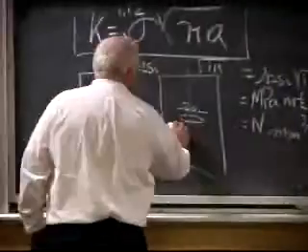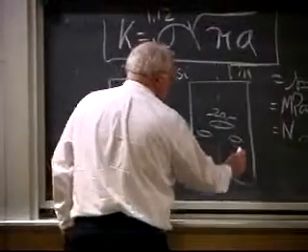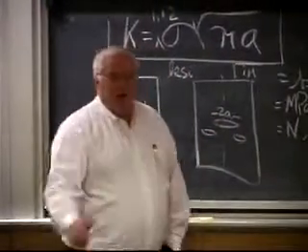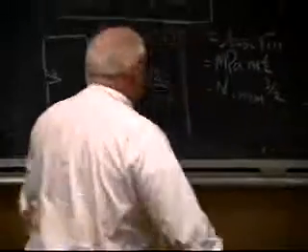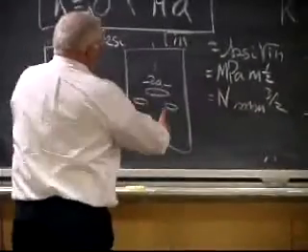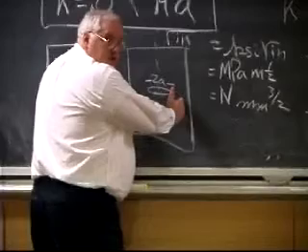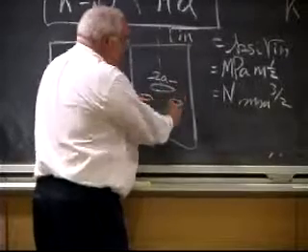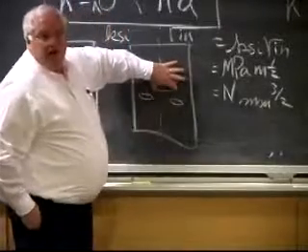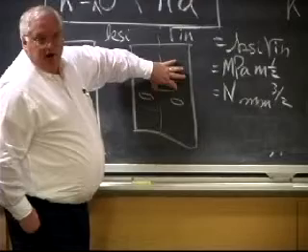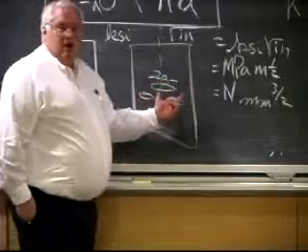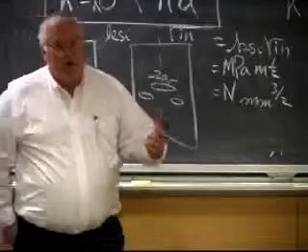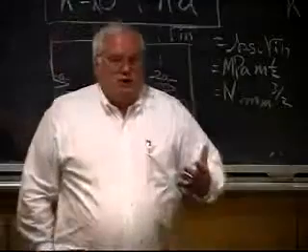What your question is asking is, what if I have a cluster of defects, right? Turns out the mathematicians can't handle that. And basically they say, in the worst case, you say, okay, well, let's treat it as if the whole thing is one big flaw, right? The limiting case is, well, you treat each one as the smallest flaw and calculate that and assume that there's only one flaw. In the worst case, you take all of them and link them together as if they're one flaw. The real answer is somewhere in between.